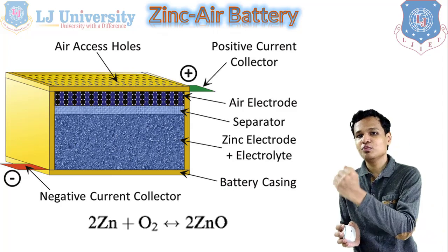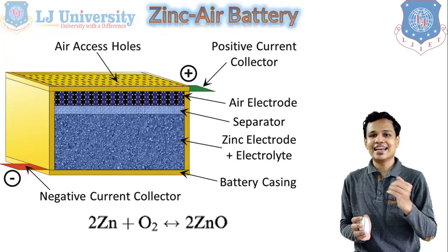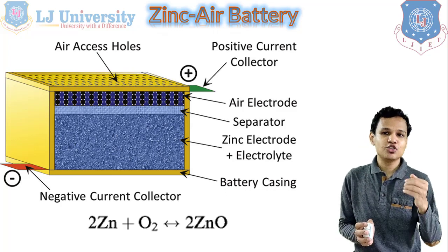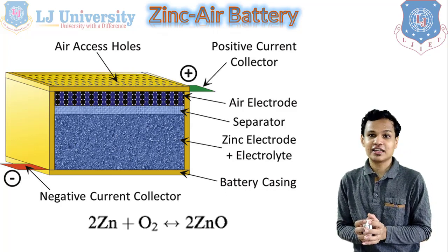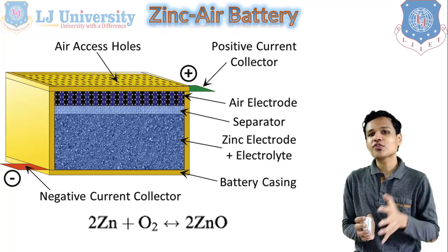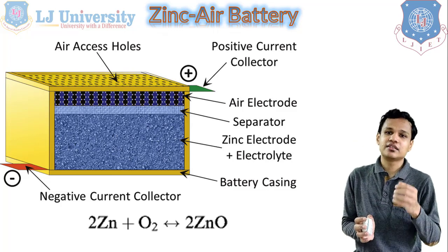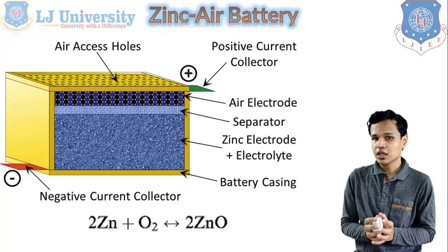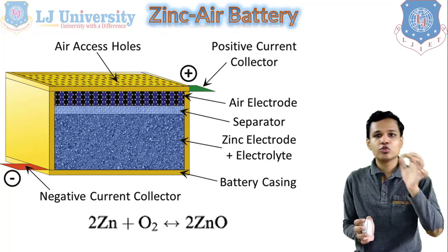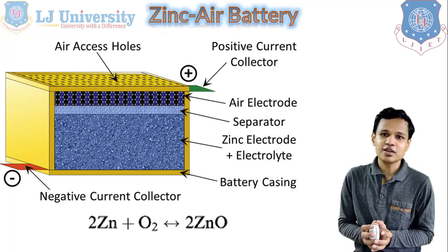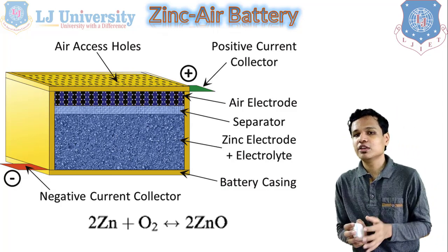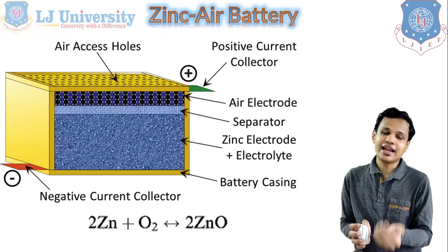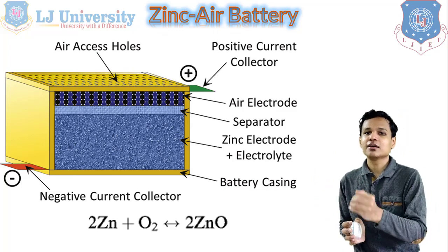Only water can be used if we are using an electric charging method. Now the air batteries can be used with a mechanical charging method as well. In the case of the mechanical charging method, the zinc electrodes will be removed by an automatic robotic method. That zinc electrode will be put on a mechanical charging method from which the zincate will be created, and after the zincate again the zinc will be restored, and that zinc can again be used in the battery.